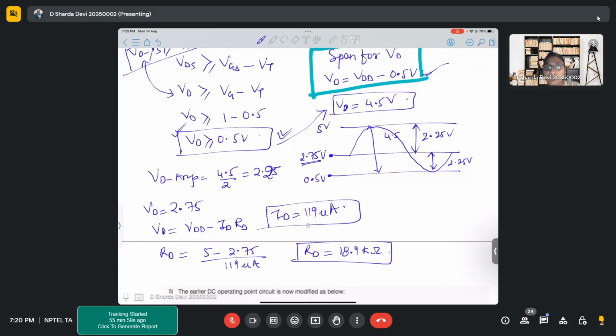Yeah, actually I have one question. Ma'am, when I'm designing this circuit in 130 nanometer, my positive cycle is not going up to 1.3 because I'm keeping VDD equal to 1.3 volt. So there is some distortion. Actually the gain is around 2.25, so it is not going up to 2.25. That much amplitude I'm not getting.